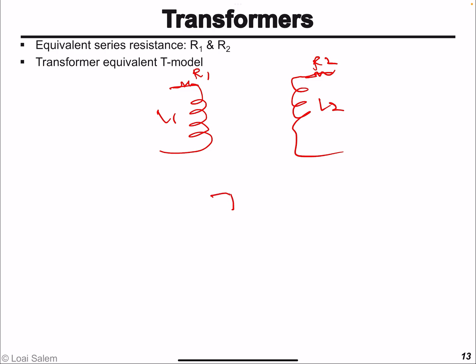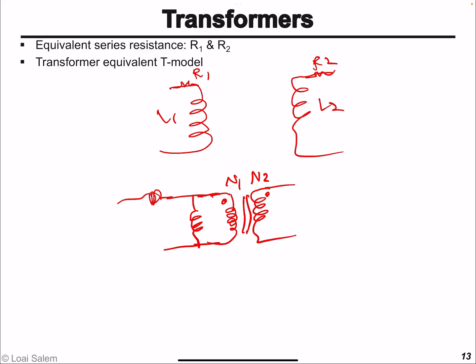So starting with the ideal transformer, this is the ideal transformer symbol, as perfectly coupled coils of certain turns ratio, say N1 to N2. Then to account for phi 11, the flux that doesn't reach the secondary side from the primary side, we said this is going to reduce the voltage that reaches the secondary side from the primary side. So we established a voltage divider, 1 minus K times L1 and KL1, so that we reduce the voltage that's applied across the primary side of the ideal transformer to reduce the voltage that reaches the secondary.